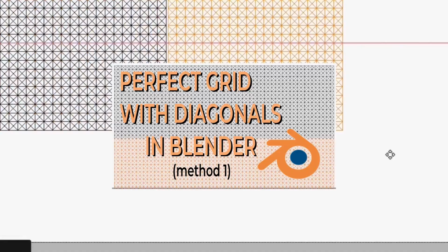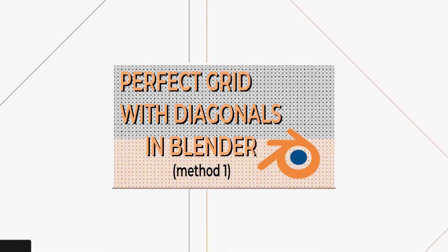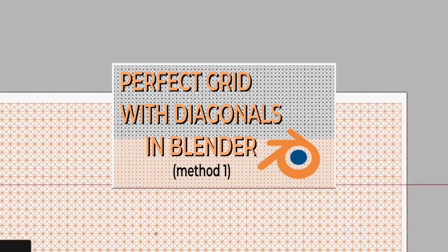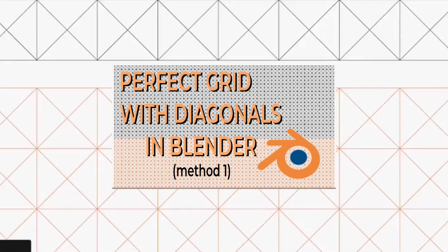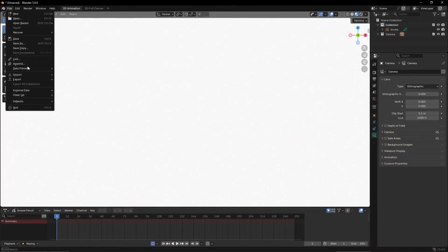We'll need a grid to guide us. In a previous tutorial, I showed you how to create a custom grid template in Blender. If you haven't seen it yet, I've linked it above. If you have already made the grid template, follow the next steps to import it into your drawing project. Go to File, choose Append to import that grid into your project.